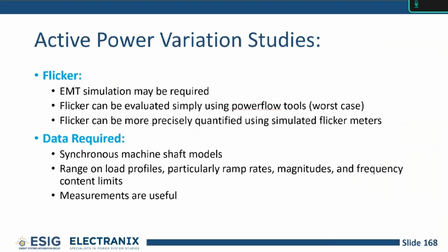One part about that, so one of the new LED lights, basically what causes visible flicker is not the flicker in the traditional sense, but the harmonics that will translate into flicker in the LED lights. It can be harmonics, but it can also just be a voltage dip. If you dip the voltage, the light will go off and come back on. Also, like the harmonics, will cause flicker. Yep. Harmonics is a separate problem.